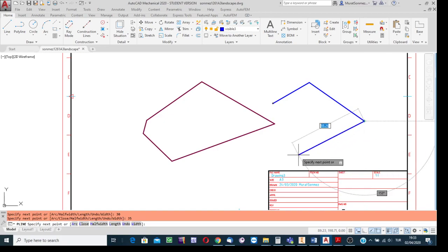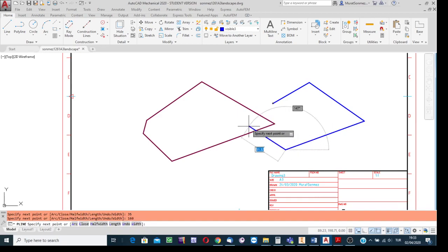Say that the length of this segment is 100. Click on the tab key. Inclination angle 160 degrees. Press enter. Okay, and then one more line. Say that it is over here. And then the closing line. Use the snap facility. That is it. But you see it is automatically defined as a region. No need to apply the region definition process.